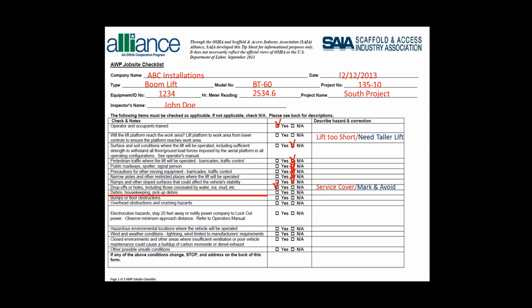So I'm going to say again, we have a hazard and we need to manage that hazard. The next one, we have debris and housekeeping. We need to pick up debris, not only on the floor where the platform is to be used, but also in the platform itself. We don't want to drive over the debris because it could cause instability of the machine, and debris inside the platform could lead to slipping or tripping hazards inside. But for this virtual website, we don't have that hazard, or we've taken care of it.